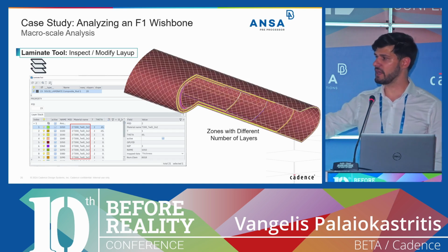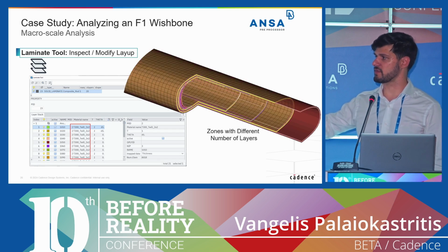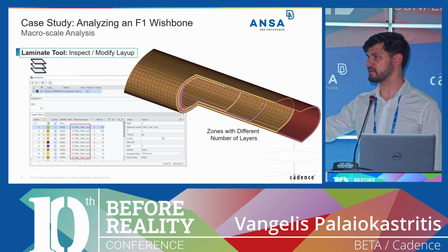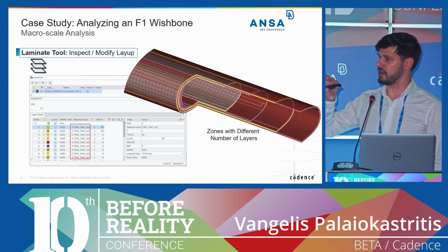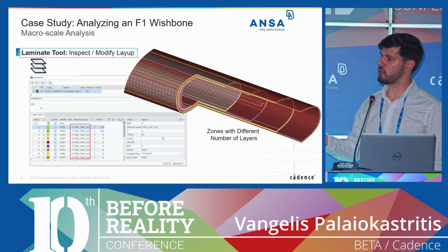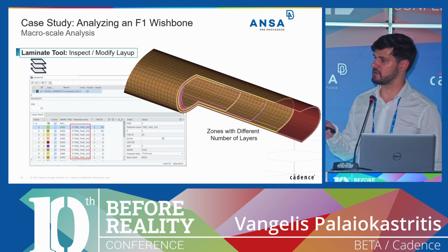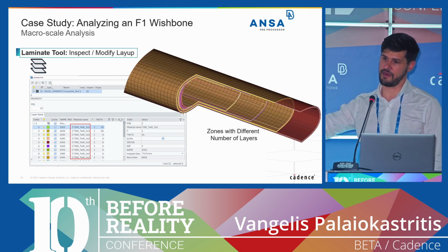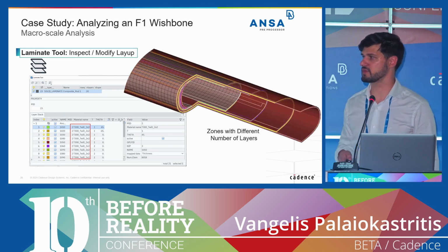Up to this point, again, we are solver neutral, so this is a solid composite laminate that, let's say, is solver neutral. So at this point, through the laminate tool, we assign the Abaqus material that exists in our ANSA session from the previous homogenization procedure.